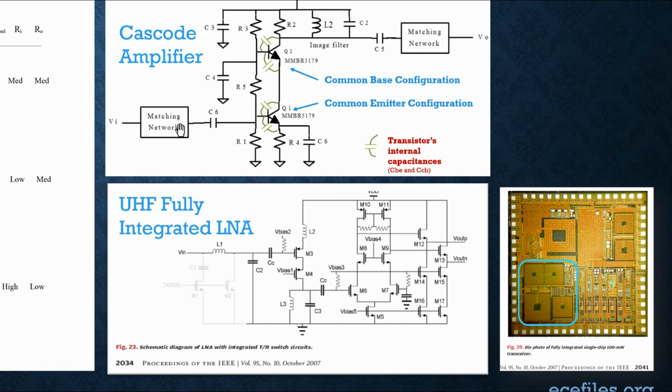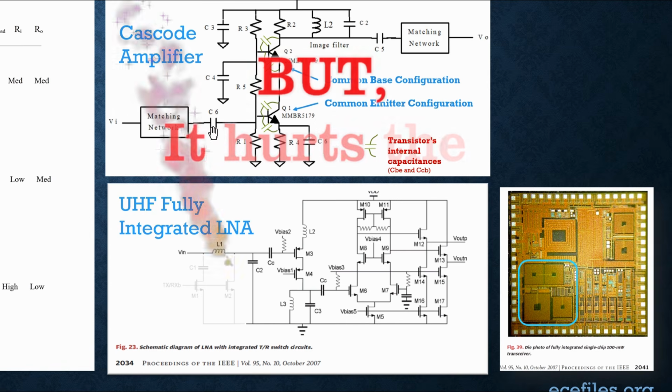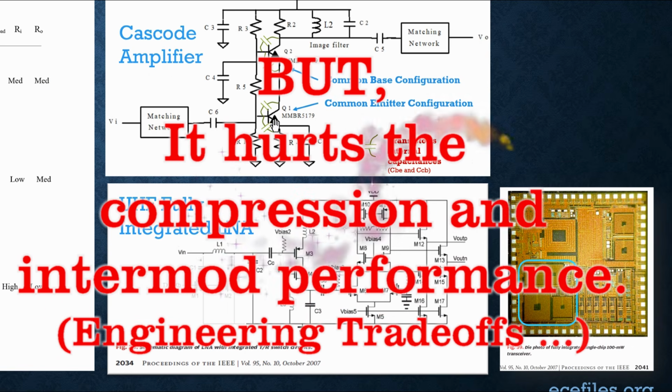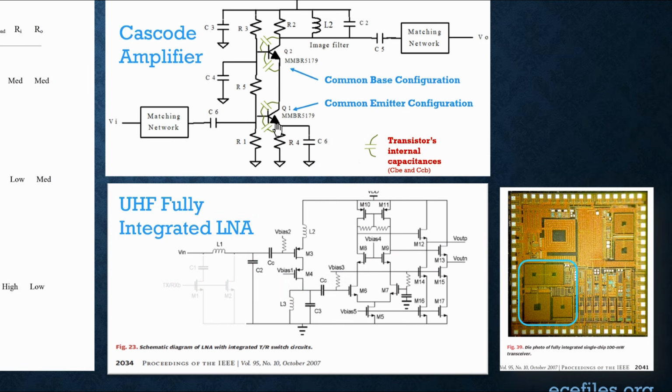And in the process, you get a voltage gain, and that really helps lower the overall noise. Because remember, the more signal you get into this thing, the better it does competing with noise generated in the transistor. So that's done right here with this so-called L match. So the voltage here is higher than it is at the input because we're converting to a higher impedance.